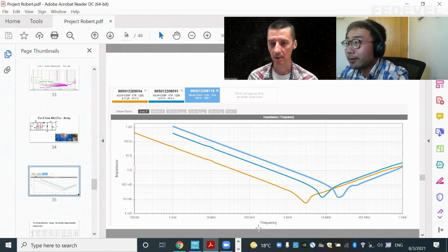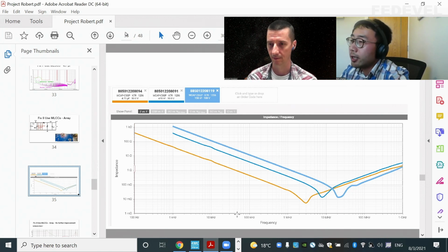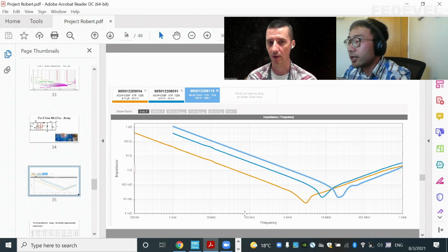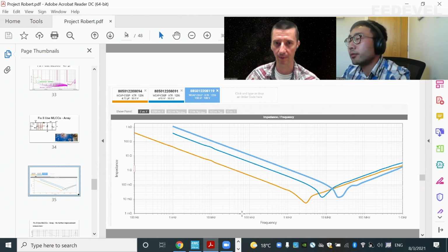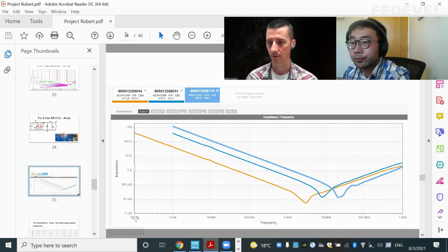Is this not going to make more problems in the lower frequencies? Not necessarily. Often the resonance is caused by the bigger value capacitor. So if you use a smaller one, then it's not going to interact with the structure of the PCB. Yeah, not often.